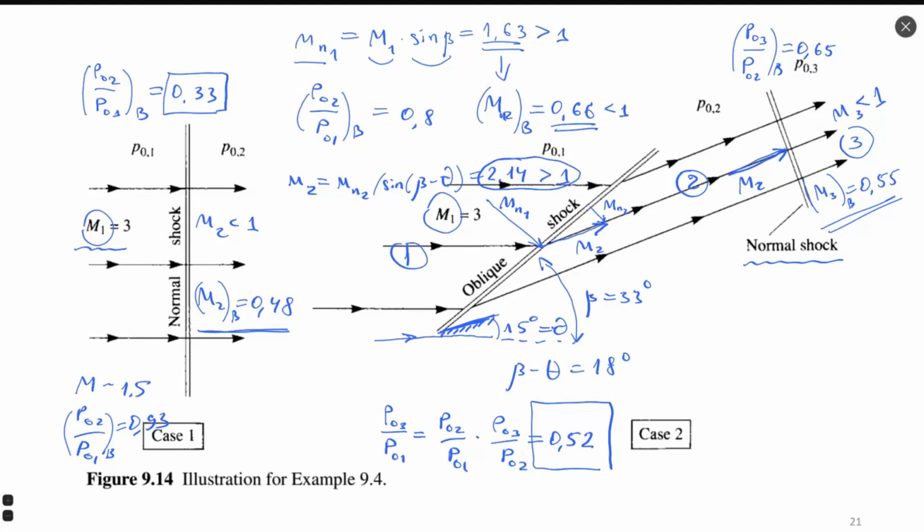So for Mach 3, usually we need a more sophisticated flow structure. This more sophisticated flow structure is, for example, a 3 shock wave diffuser, very similar to case 1, where we have geometry that creates one oblique shock wave. Then we have a change of geometry which creates a second oblique shock wave, and then a normal shock wave at the entrance of the diffuser.